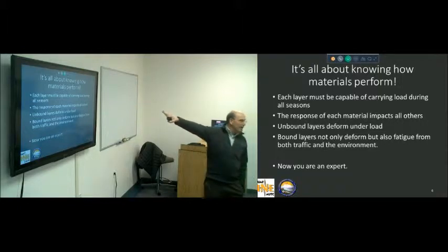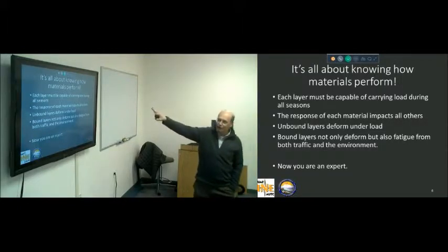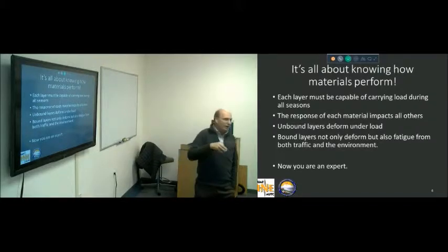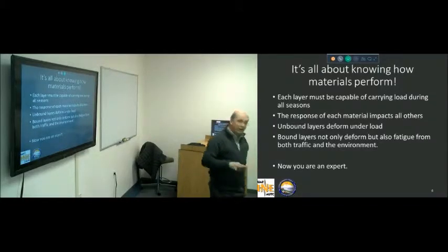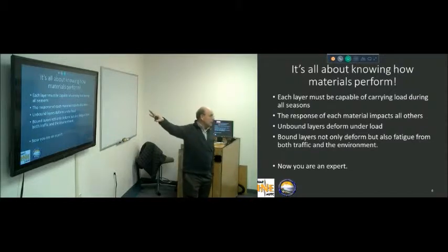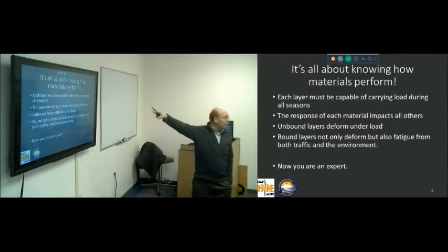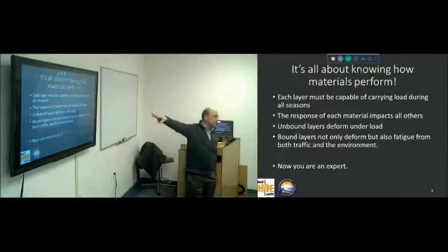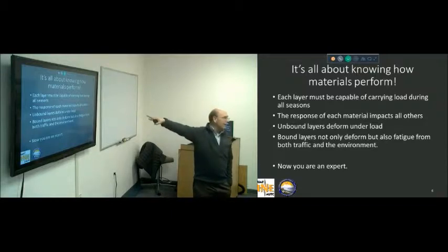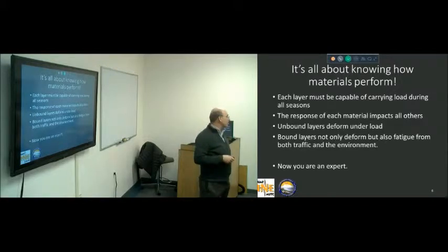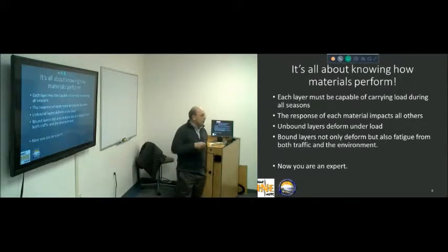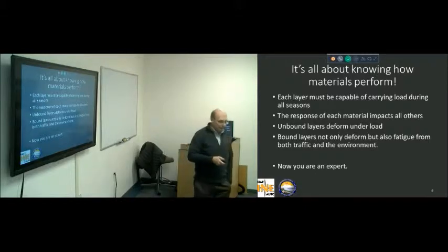Okay? This is really all you have to know, these 4 points. And if you truly understand them, then you're going to be just fine. Unfortunately, very few people truly understand that. And that's where most of our failures occur. I've been involved in dozens of forensic engineering investigations on pavements that have failed, and it failed for one or more of these reasons every single time. It's not because somebody didn't run the software right. It's not because somebody didn't punch the buttons right. It's because they didn't put in the right material properties that truly represented what's going on.